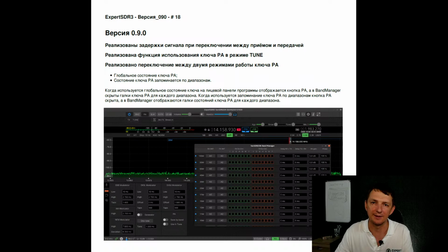It means that you put the radio to TX mode and you press a foot switch, maybe my mic button or something else, and the radio goes to TX without signal. We called it cold switching, without signal. And then after the delay time the signal goes to transmitting.